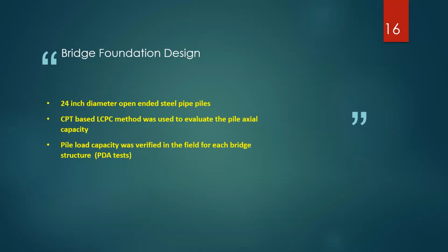Now, I want to emphasize that even though we used the LCPC method, it's very important to appreciate that, given the abundance of data that we have here and the calibration that we did side by side, and the lab testing and other elements in this project, one can easily use this data, or help that data, to come up with a site-specific design method using CPT for these types of foundations. And we also had the depth of the plug in the soil at the bottom of the foundations measured during construction as well. So we have that data as well.